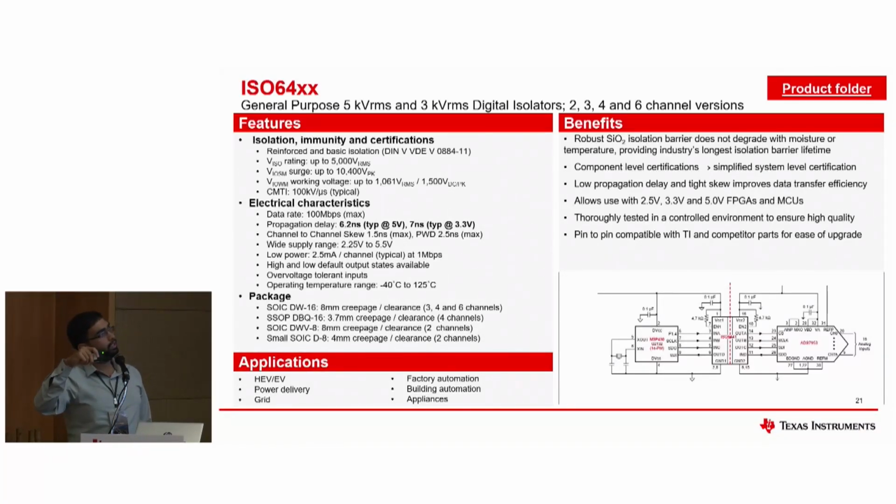This used to be a violation of absolute maximum ratings from the datasheet in our previous devices. So everything needed to be shut down. Let's say you have a complicated MCU which is getting used for some other application in parallel, and you are also using the same power line for the isolator and this one.